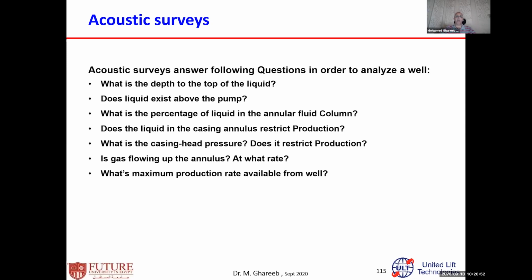You measure fluid level at two different times. For example, now, then I close the casing for about 15 or 20 minutes, and I measure the fluid level again. I measure the pressure build-up. There are special techniques in here. If you go to the Echometer website, you can find a lot of information and animations on how this works. Really, there is very good information, and if you search the website about acoustic fluid level measurements, you'll find a lot of information.